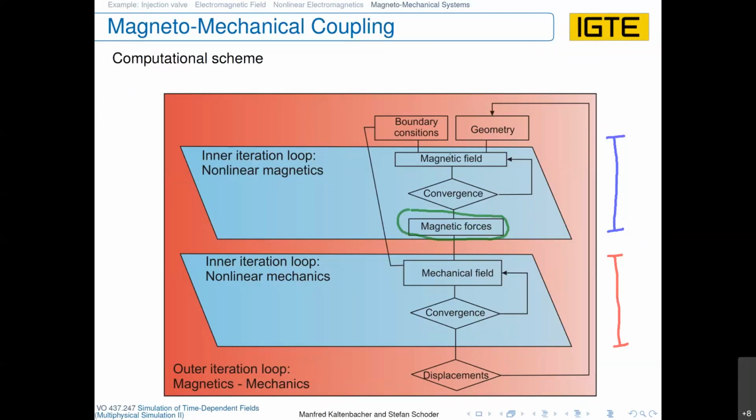So you compute this kind of pseudomechanics to get a new deformed mesh which is consistent and where you can compute the magnetic field. If this is not possible, you have to remesh for the computation of the magnetic field. Yeah, and if you have a new magnetic field, you get new magnetic forces, and you go to the mechanical field, get a new mechanical field, new mechanical displacement, and check just the convergence criteria we have discussed.